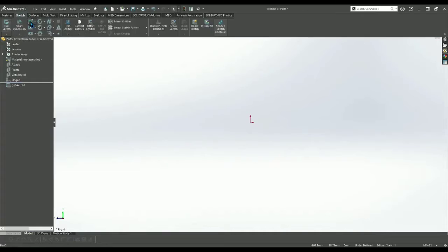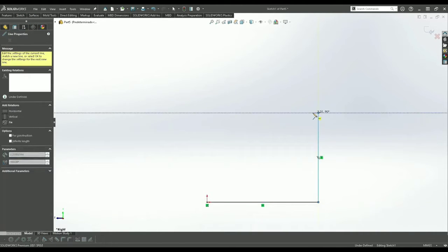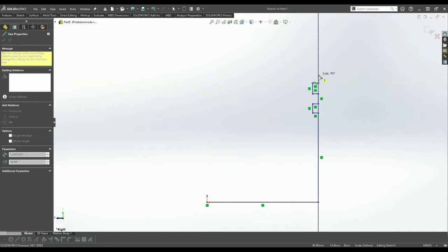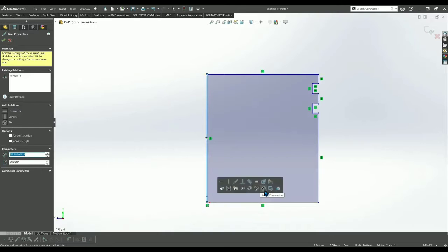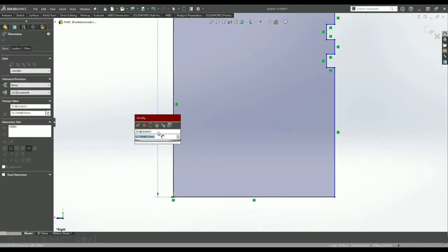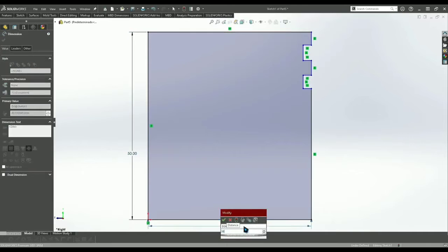The first step is to draw the geometry of the piece into dimensions on a plane. That's as if you were drawing on a sheet of paper. SolidWorks makes the process easier for us because it's a parametric software, which means that we can start from an ambiguous drawing and later add parameters to it to fully define the desired geometry.